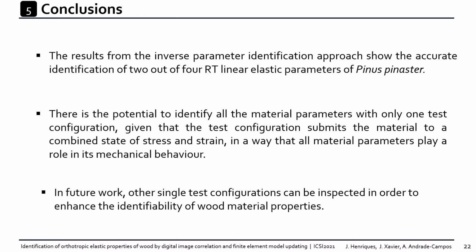Presenting you the main conclusions of this work. The proposed methodology, based on a single uniaxial compression test to simultaneously identify 4 orthotropic elastic parameters, proved to be effective in identification of 2 of the 4 RT linear elastic constitutive parameters of Pinus pinaster, being the modulus of elasticity on the radial direction and the Poisson's ratio on the RT plane.